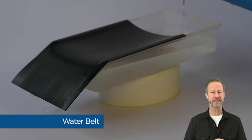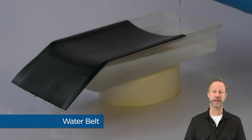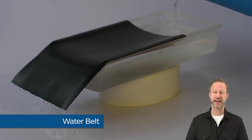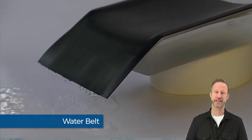In most installations, Waterbelt is installed with the slots facing down for two primary reasons. The first reason was demonstrated earlier, where saturation of the pore space generally starts from a buildup of water below, the same as filling a glass of water. The underside of the belt is perfectly positioned to intercept the rising water.